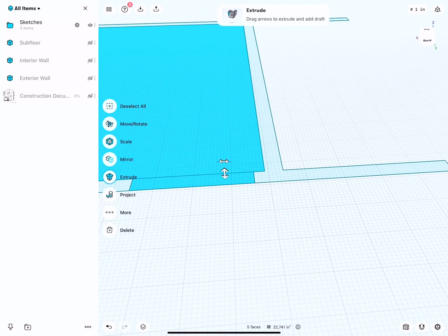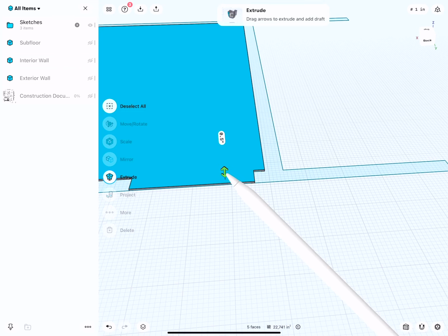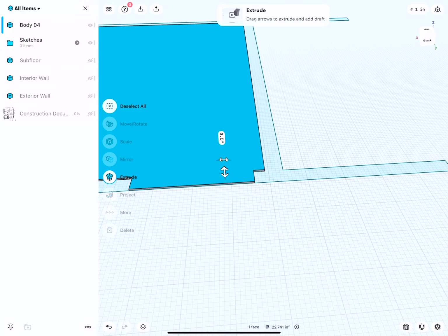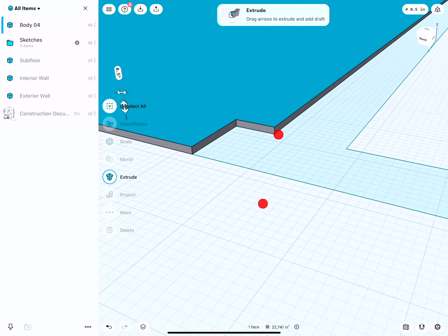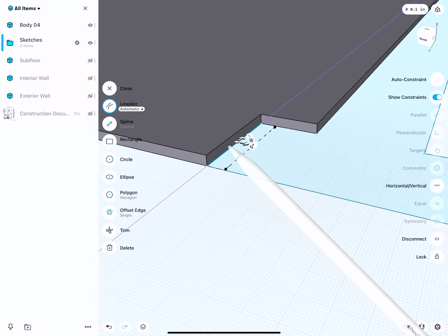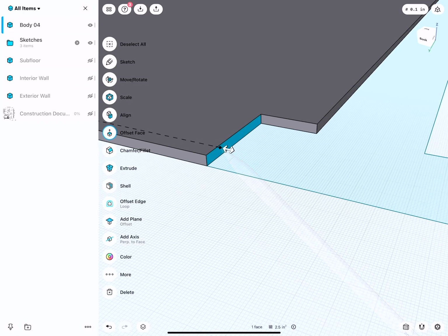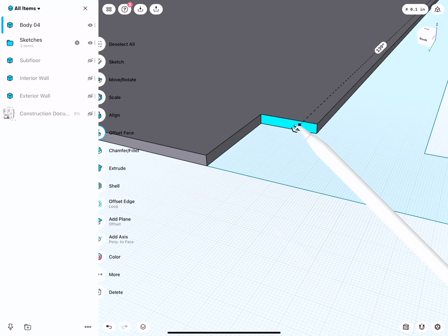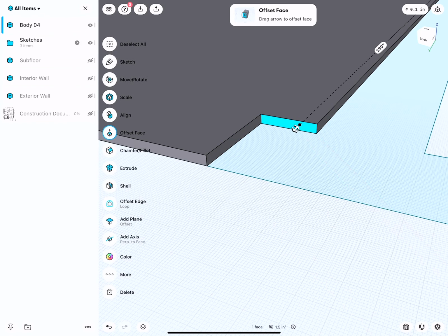So one approach would be, I model this up by 1/2 inch. This is based on a material sample I have of 1/2 inch thick hardwood floor. So this dimension has to be matching the type of floor height you're going to use. And I said that this actually remains where it is, but this has to go back 1/2 inch.